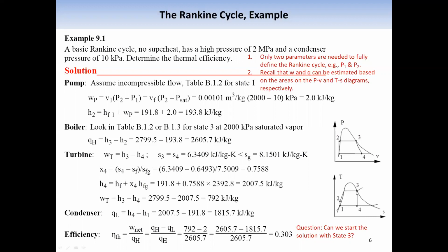And from its entropy, we can calculate the entropy, and the pressure for state 4 is known too. So we can estimate the quality for state 4. So we can do similar calculations for state 1 and 2.